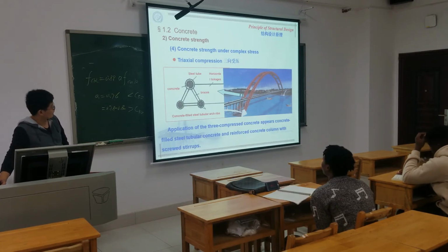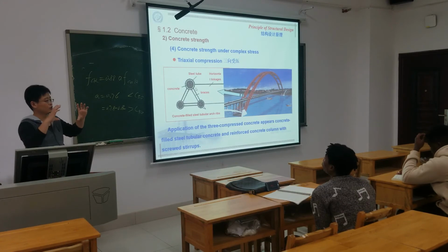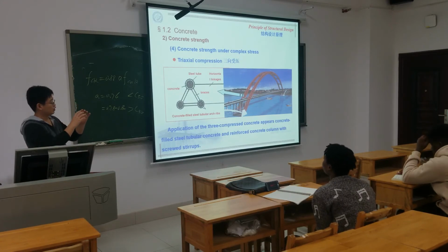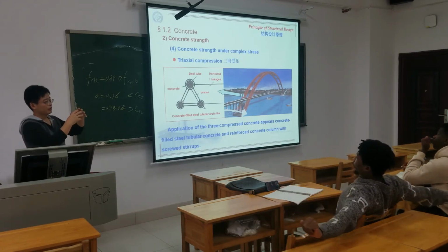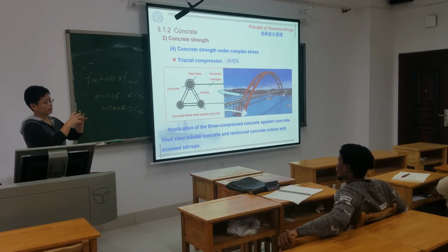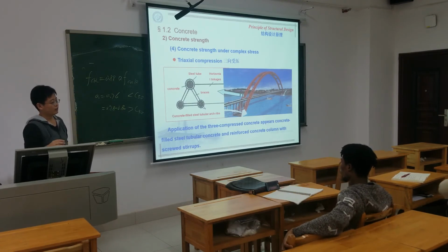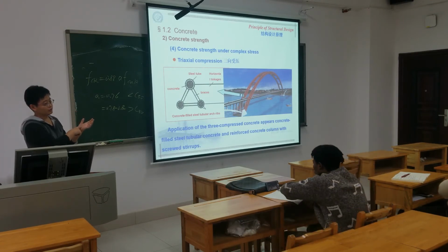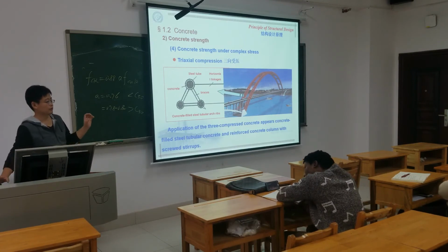But the disadvantage for concrete-filled steel tube is that sometimes the concrete inside cannot be filled so tightly. Sometimes the concrete and the tube may be separated, not connected together tightly. So in this region, the force is different from the original design force.